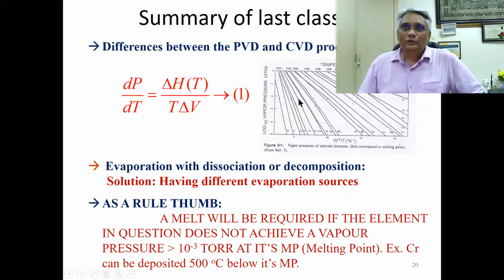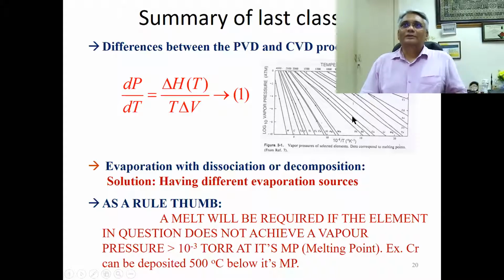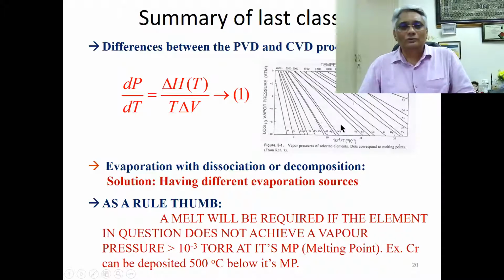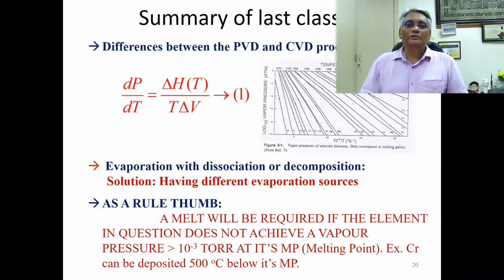And in these plots, you get information about the melting points of the system. These give basically guidelines as to what kind of alloying is possible and what is the information with regard to the vapor pressure when you're thinking of making an alloy composition or an intermetallic.